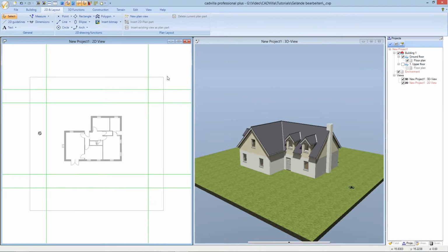To your information, we will edit the terrain of our house so that in the front and in the back of the house is a slope with a height difference of 2 meters to the ground level of our house. This area will be on a level of -2 meters. This area is the slope to the ground level. The ground level will be on a level of 0 meters. This area is the slope to the next level, and this area will have a peak of 2 meters and then a slope down to -2 meters.